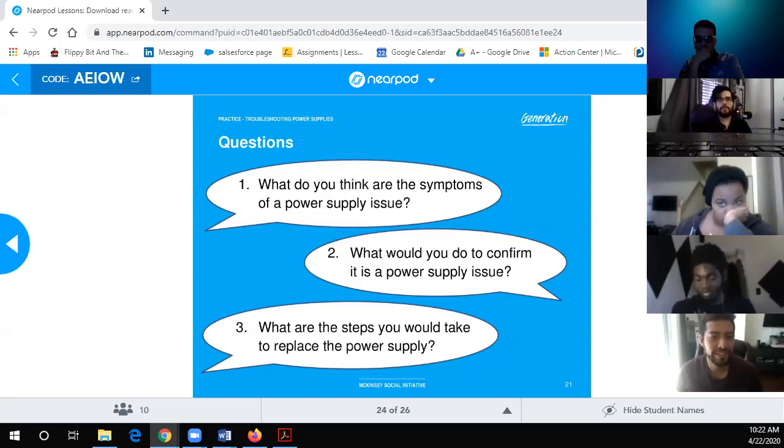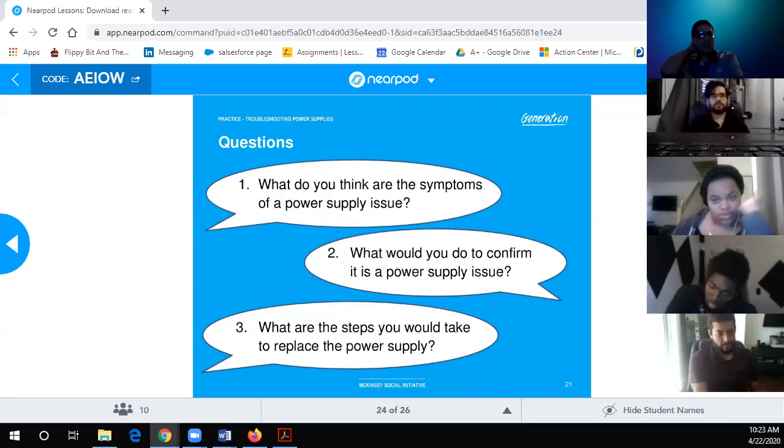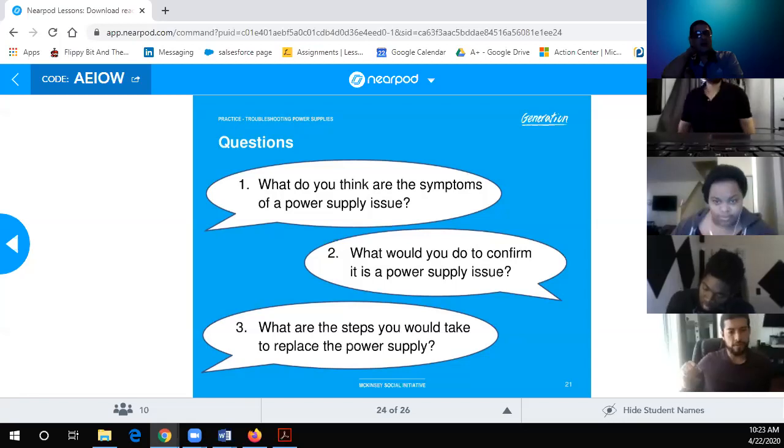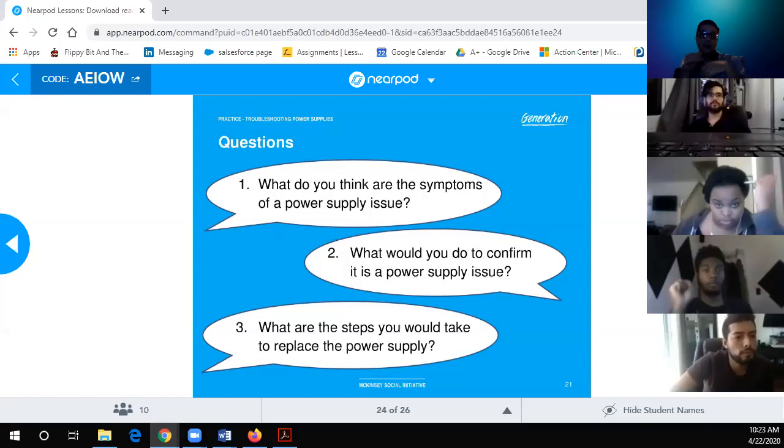When you start your computer and it's stuck on BIOS as if it's frozen, it's a sign that the power supply is slowly dying sometimes. In my case, it was. So it's turning on, right? The power supply locks up and dies slowly when something's happening with its circuitry inside. It does turn on, gives you the impression everything's fine, but it just doesn't work. That's definitely one of them.